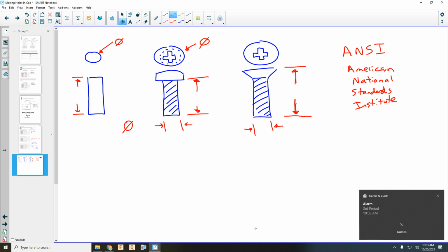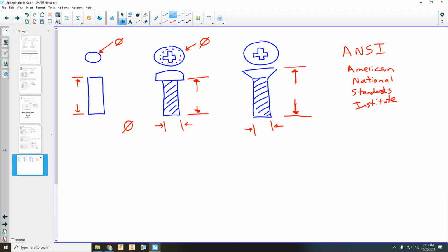Okay, so we are partway into our first step in our reverse engineering project. We will be moving along just fine. We had our 2-minute warning. So that's the first thing we need to do as our bell ringer tomorrow. We need to get our measurements with our dial calipers. And then we'll see, hopefully we all get the same thing. We should not have as much variation with the calipers on the steel parts as we have with the plastic parts, because they're all the same and they're all bought at the same time.